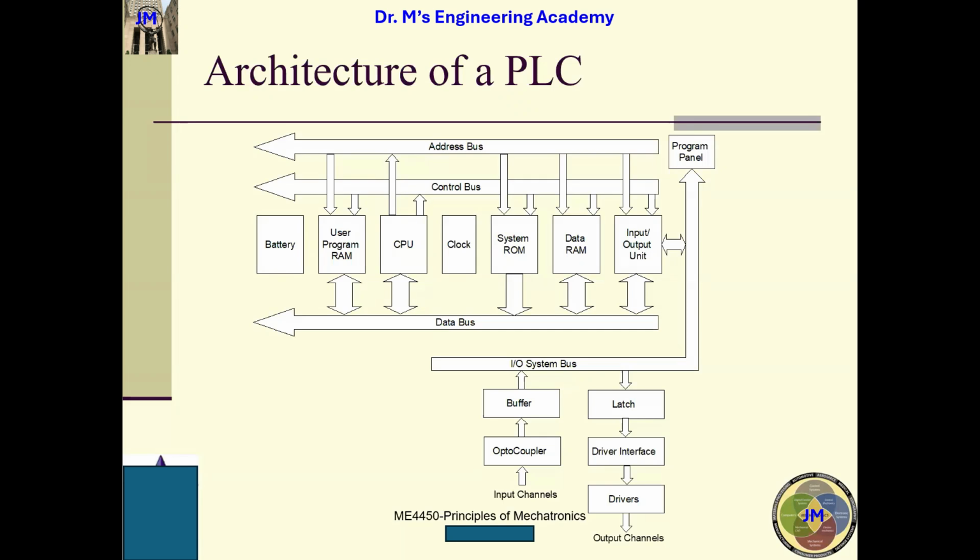However, the PLC is driving devices that sometimes might be 110, our daily life appliances, and maybe 240. So we do not want these two systems to be connected together physically, and what we should do is use an optical coupler.